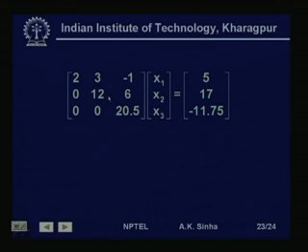Gauss elimination is, of course, the simplest of these methods and is quite effective and very much used for solving the linear set of equations which come out of the Newton-Raphson load flow equations. So, this is what we will do today, and in the next class we will talk about how to solve the Newton-Raphson power flow equation using this direct solution method.